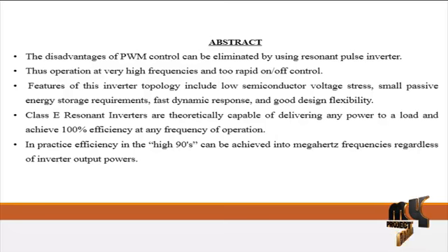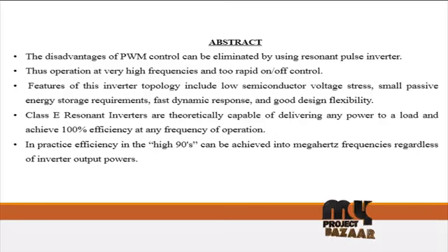These features include low semiconductor voltage stress, small passive energy storage requirements, fast dynamic response, good design flexibility, and so on. Generally, Class E resonant inverters are theoretically capable of delivering any power to a load and achieving 100% efficiency at any frequency of operation. In practice, efficiency in the high 90s can be achieved into MHz frequencies regardless of inverter output powers.